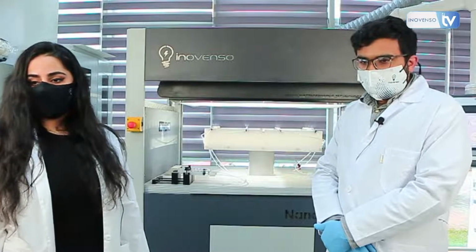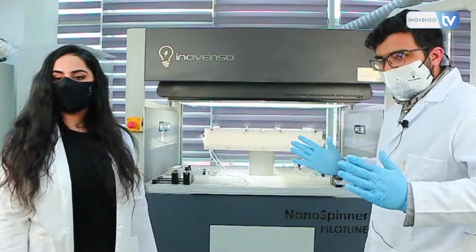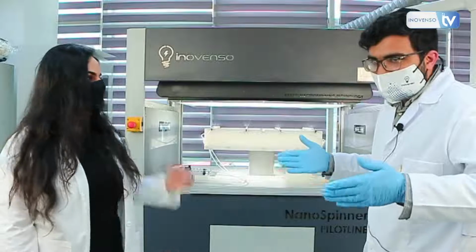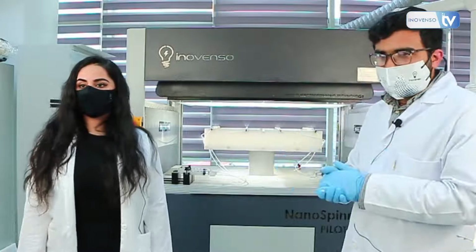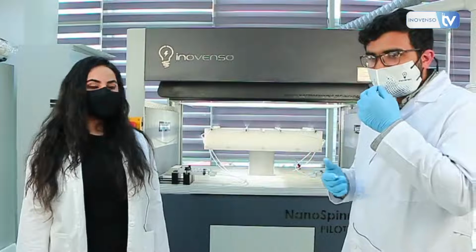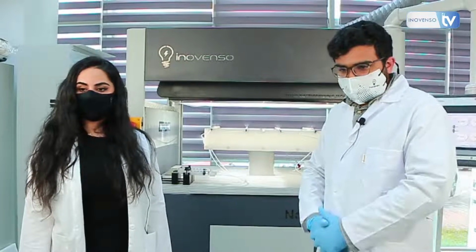Another one: what is the basic challenge of your PE550? What is the maximum size that we can produce? The reason why it's called the PE550 is because the width is about 550 millimeters, or in other words, 55 centimeters. So that's the constraint when it comes to width, but it can go up to several hundreds of meters, like up to 600 meters in a roll, while you're synthesizing nanofiber rolls on substrates.